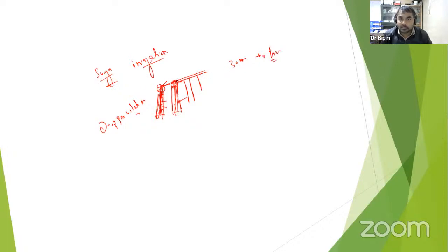Again, for a short period of time with high velocity, we apply the water in this furrow. Again, then we will apply in this and this. It is dependent on the size of your field, how many furrows you have. After 30 minutes, you may again apply the water in this.